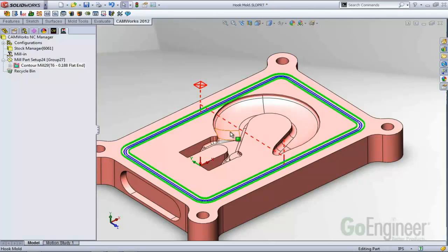Not only did I save the tool, but I adjusted the feeds and speeds, I adjusted the depth of cut, the side allowance, I created some lead-ins and some lead-outs, and I spent a few minutes perfecting this toolpath. And also assume that this O-ring groove is a feature that I machine often. Enough so that I don't want to create or spend the time adjusting those parameters every day, or even more than once. What can I do?